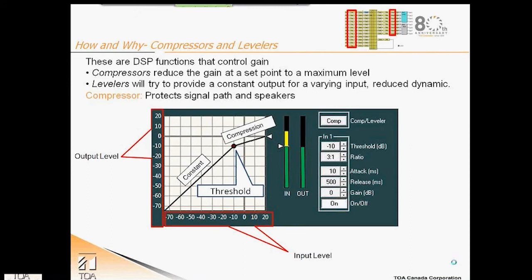We are finished with our discussion of filters and now move on to another class of DSP used to manage signals at the input and output. Compressors have the ability to attenuate signal based on the signal level and at what point we would want the signal to start this attenuation. The compressor will pass a signal in a linear fashion unaltered until the set threshold is reached. At this point, the gain is reduced at a fixed amount until the maximum allowable level is reached.